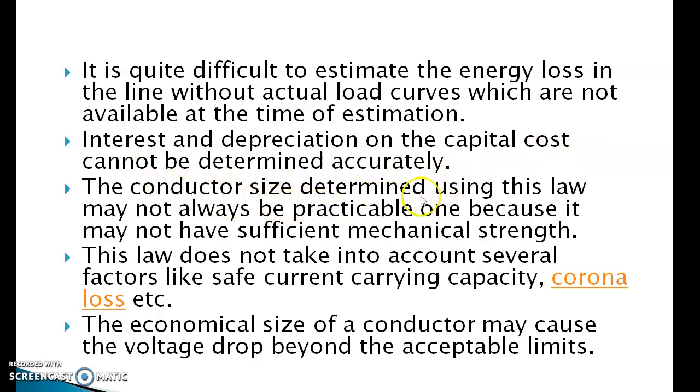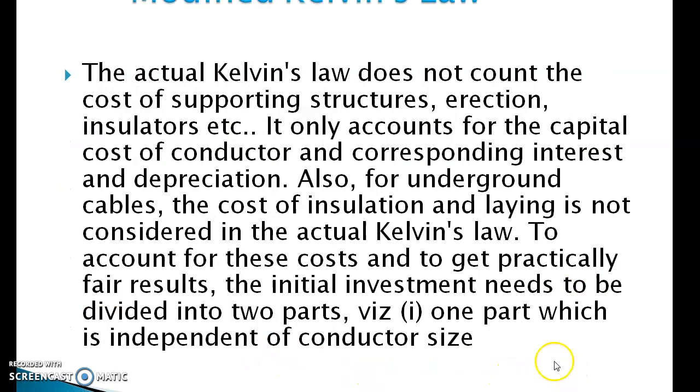The conductor size determined using the law may not always be a practicable one, because it may not have sufficient mechanical strength. This law does not take into account several factors like safe current carrying capacity, corona loss, etc. The economical size of the conductor may cause the voltage drop beyond the acceptable limit.